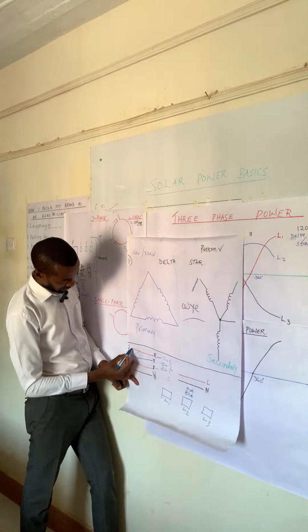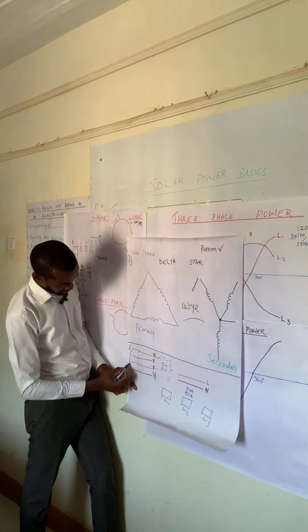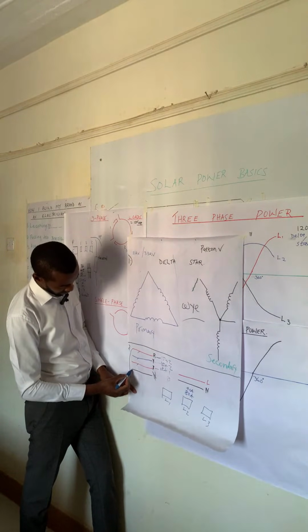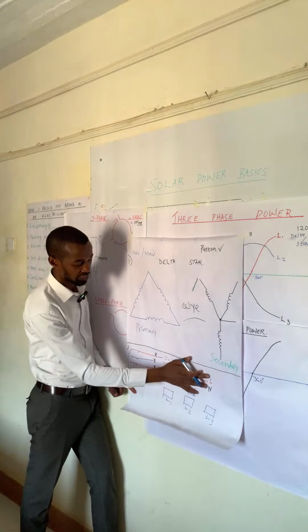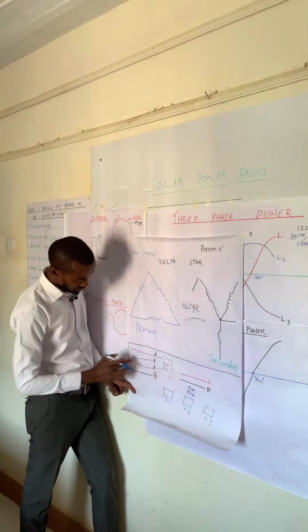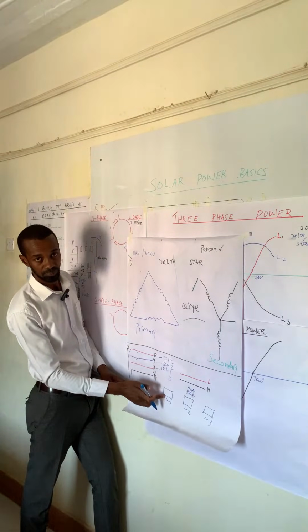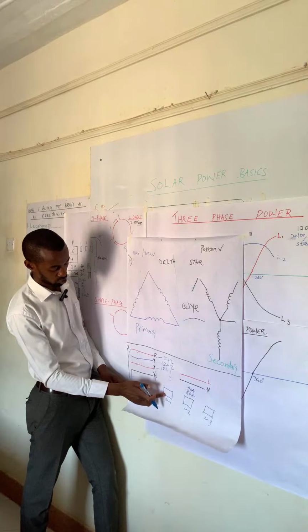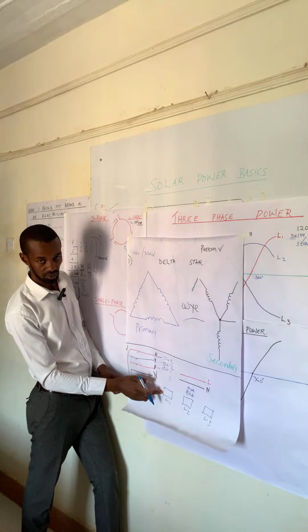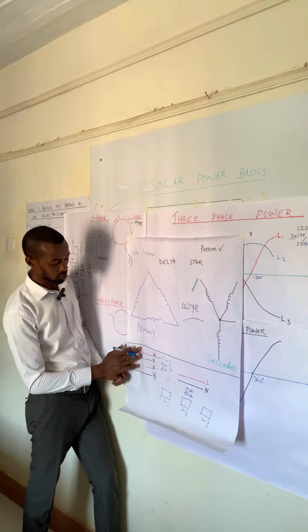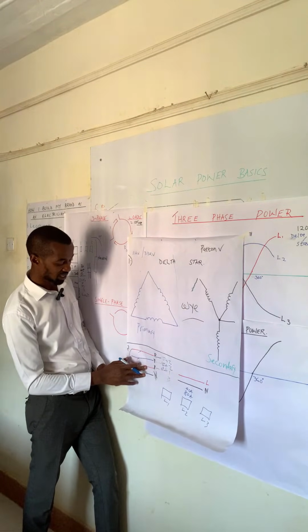Now, this company, again Kenya Power in your country, can decide to connect the red phase and the neutral all along that power line. That will definitely mean that this L1, the fuse connected to the red phase, is overloaded.